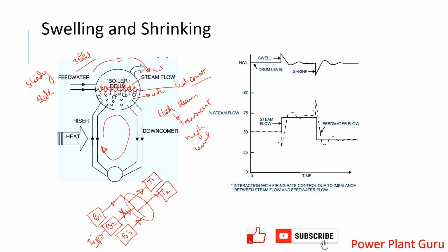Hope you understood, two points. One is water was under a pressure, and that pressure, let's say X, was maintaining this level, and the pressure became less than X in a very short span of time, then this level tries to jump up. That's one factor. Another factor is that some flash steam will be generated, which will again push that turbulence in the system, and the level will be a little bit higher. So these are the two things which will make your level high.